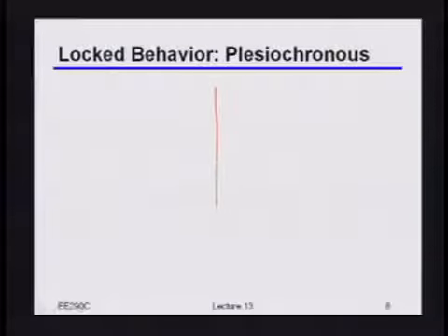So what I want to draw now is phase versus time. First of all, I'm just going to draw in blue here. If I told you that I have a frequency offset, what does that translate into from the standpoint of phase versus time? And don't worry about wrapping and things like that. Just, what's the shape of phase versus time if you have a frequency offset? Yeah, it's just a ramp, right? It's a straight line, okay?